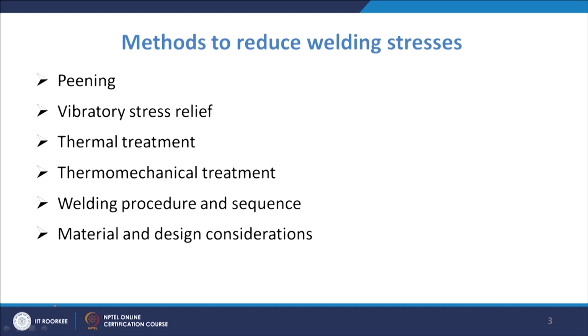On a large scale, residual stresses affect the properties of the material, because they give the material a tendency to fracture in a brittle manner. There may be an effect on the stress corrosion cracking of the material. It will affect the dimensional stability of the material.